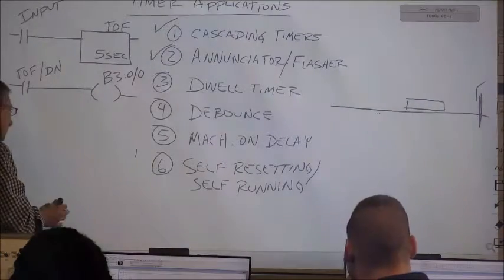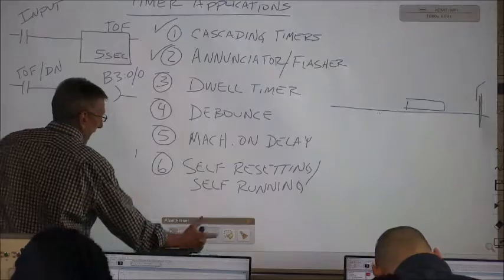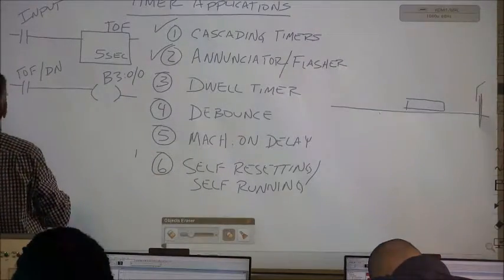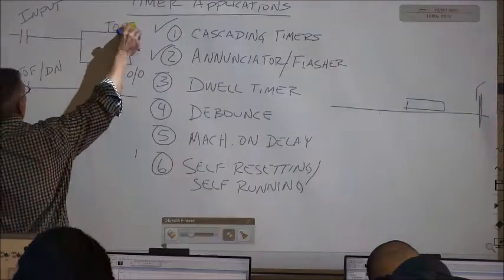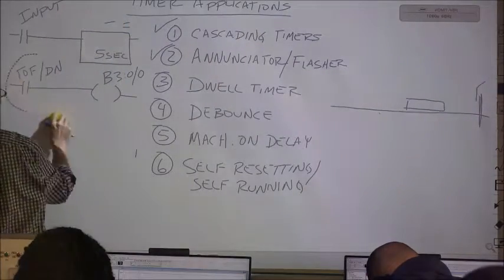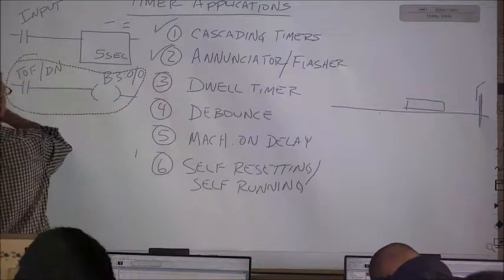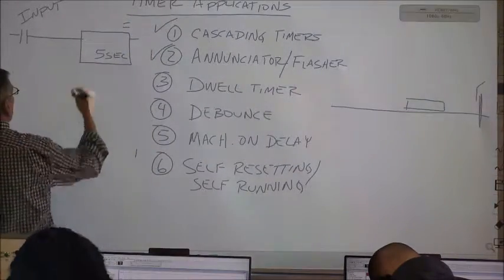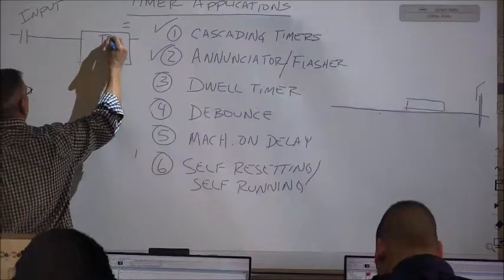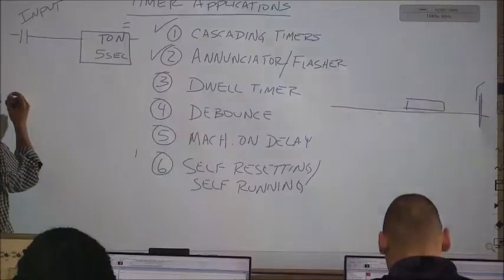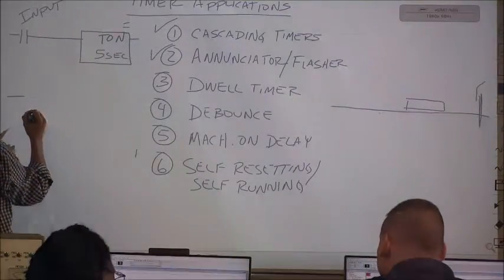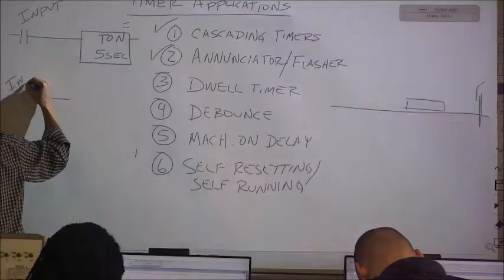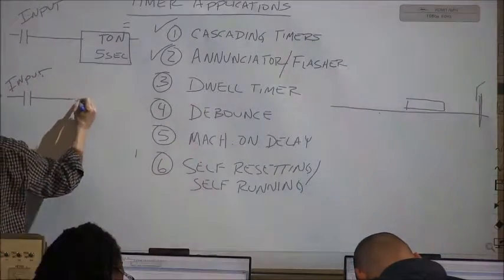Another, and probably a better way to do this, I never used it. I always used just the timer off. The first timer you set up is a TON with that input. And then you set up another timer with that same input that is a TOF.